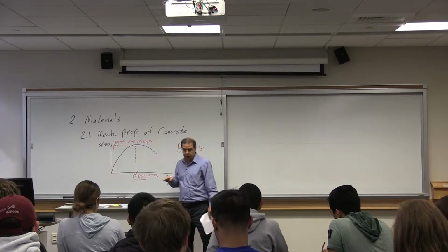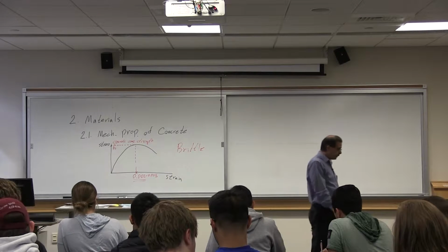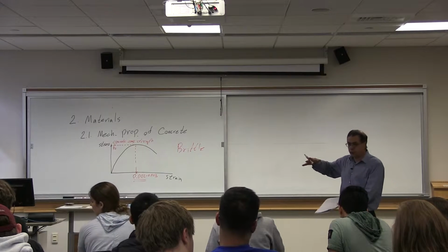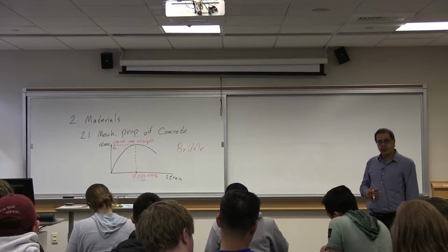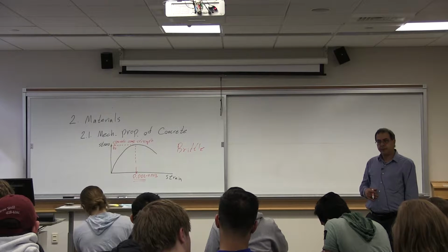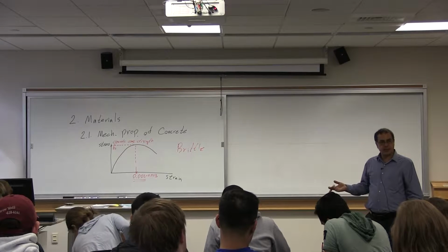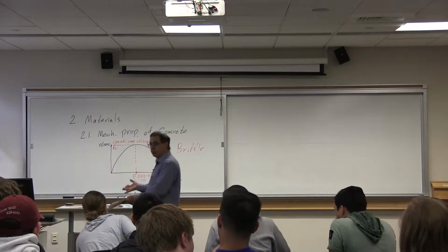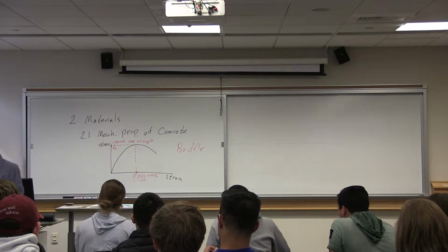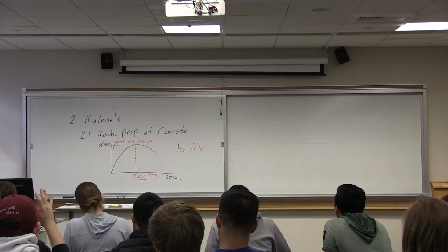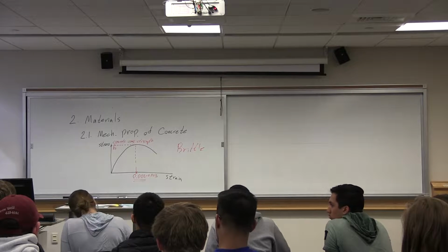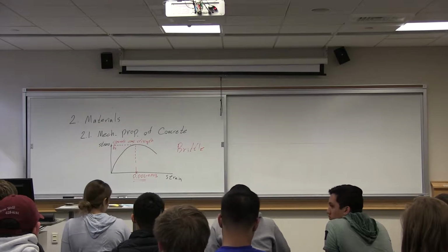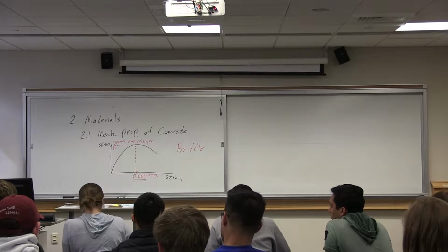The stress-strain relationship goes down. What does it mean? I mean, you are pressing it, and how could the force go down? How could the stress go down? Let's say you are doing the test. How could you manage to reduce the load? How do you know when to reduce the load? You look at it, you see when it's cracked, you reduce it. It's very difficult if you want to reduce the load.